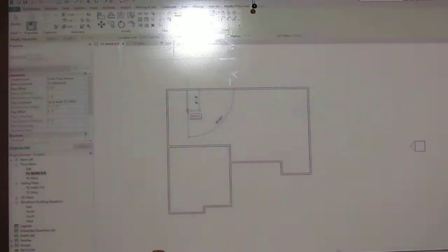So I've got on that left side of the master bedroom, see how it's got the master bath, where it looks like it's got a tub, place for a sink, and then it's got a little privacy water closet, shower. And then storage. You see on the floor plan in the top left, we've got that wall that comes all the way down. Well, all I do is come up and click on a wall and then drag it all the way through. Okay? And then close the wall.